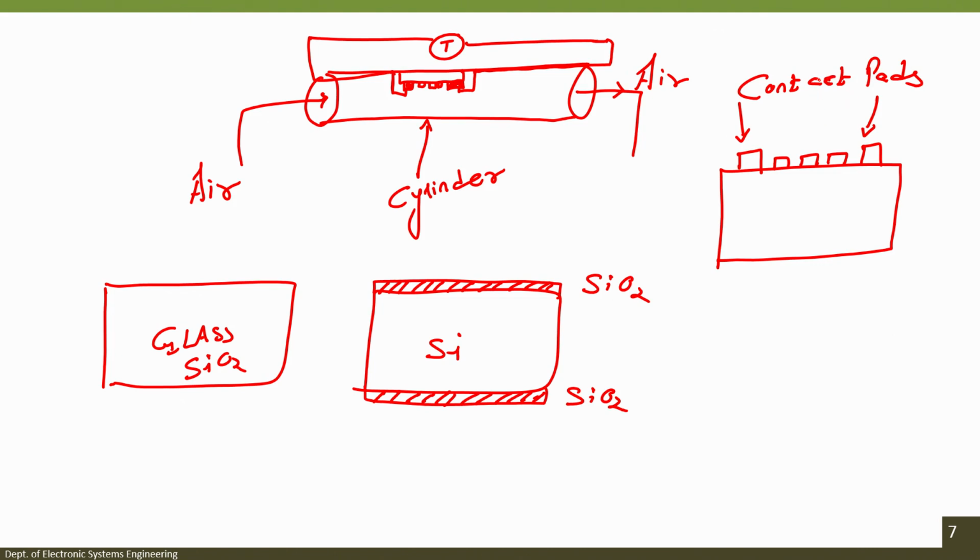These are contact pads, and the material that we will be using is chrome gold, or let us use platinum, or you can use nichrome, that is easier, nichrome, right, and this one is my glass. I want to fabricate this particular heater.